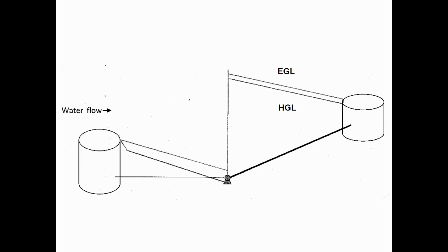But the really important part is to illustrate that in a pump, you just have a straight vertical line that represents an immediate increase in energy in the form of pressure. That's how the pump is adding the energy. So this is an iterative thing where if you don't have this going high enough, then you're not going to be able to get the line to end at the water surface where it needs to be. So sometimes you have to start at the end and work backwards when you're doing these sketches. Work backwards, then start at the beginning and work forward, and that tells you how long to make that vertical line. Yeah.